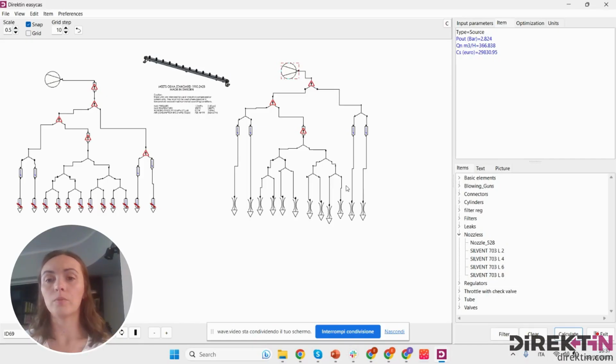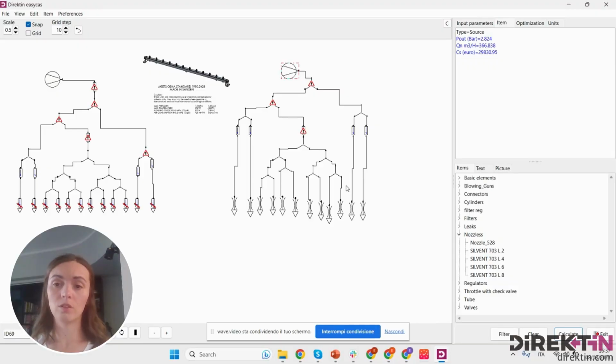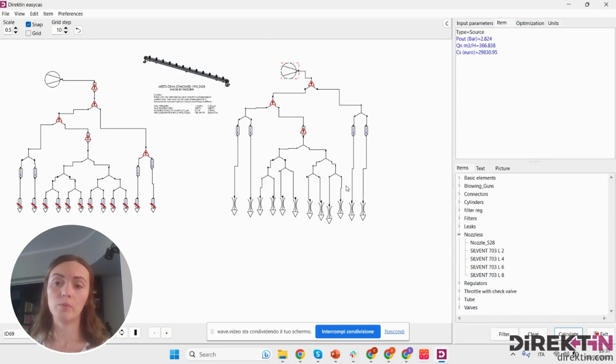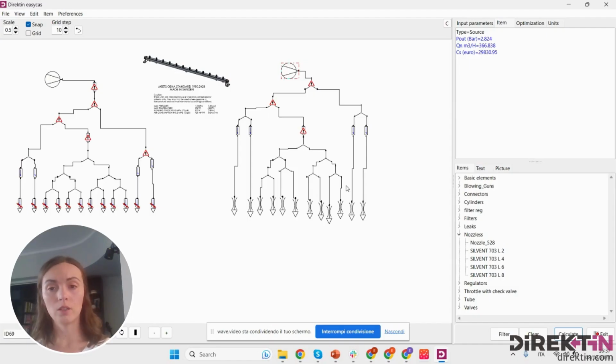And the projected application was for 120 newtons. However, the application that was really used had around 70 Newton of blowing force. And this was questionable for the operators. So sometimes they said it was fine, sometimes they said it was not good. But the main concern here is the high pressure drops downstream, pressure fluctuations inside the machine, as well as the pressure drop in the compressed air line. As the next step, we go now to model the compressed air line.